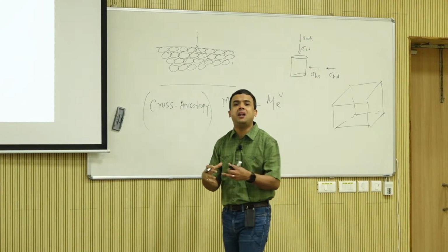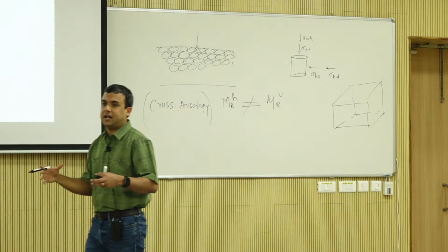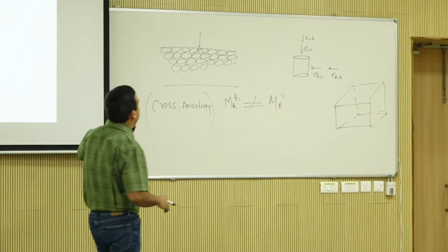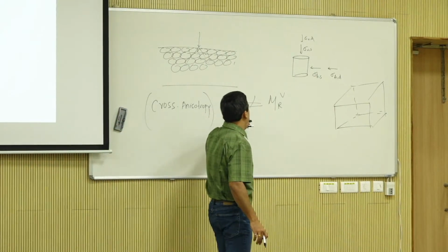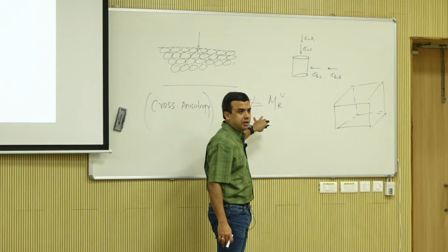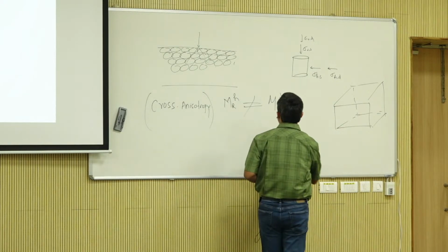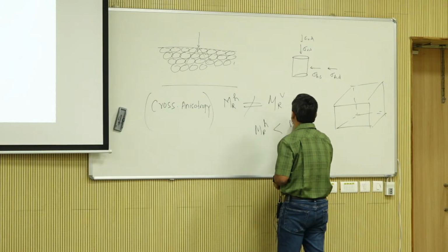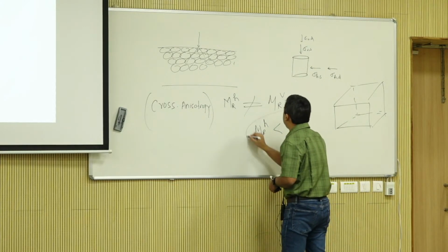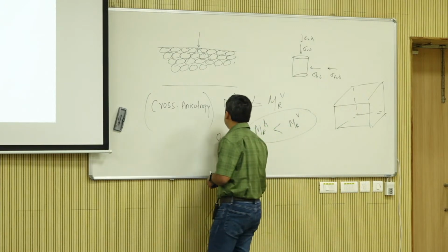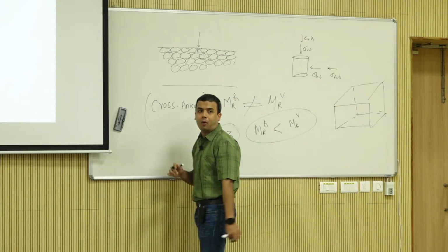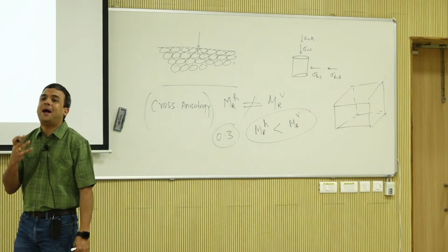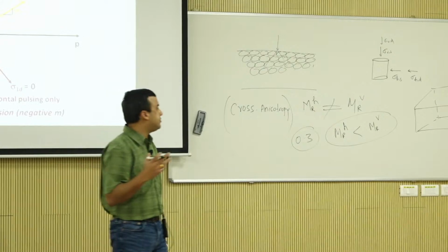So when you pulse in the horizontal direction and then you are able to measure or track the modulus values, you actually see that MRH is pretty small compared to MRV. If you look at the comparisons, the factor is close to about 0.3, about 1/3. Okay, so what does that mean? What is the significance of this?